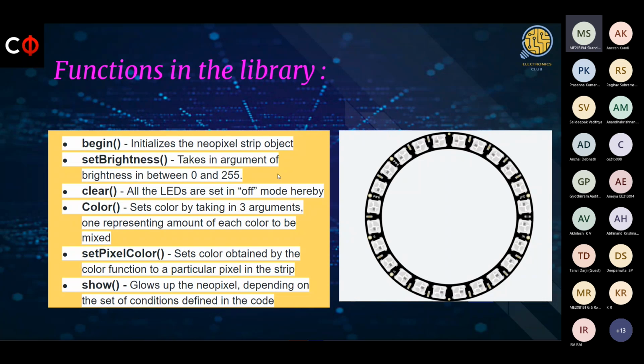So again, this is what I was talking about. And in the code, you would be seeing that the variable that we assign this color function to is a 32-bit number, that is unsigned. So that's why we have this from 0 to 2 power 32 minus 1. Unlike the case of char that you would have seen in your C program, which ranges from minus 128 to plus 127, which is a different case. I mean, that wasn't int, that was character, my bad.